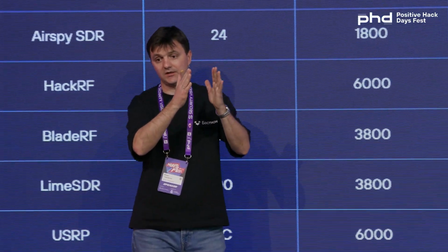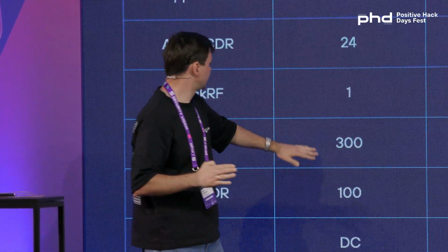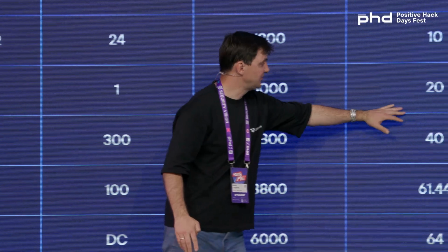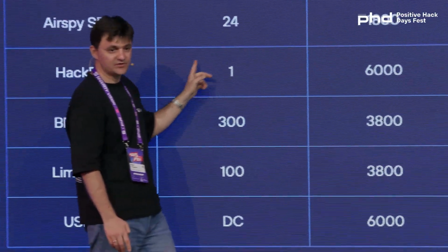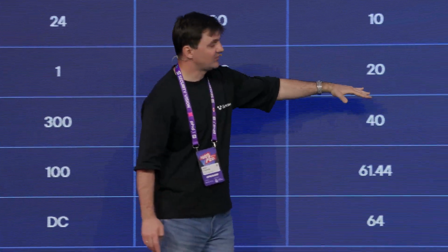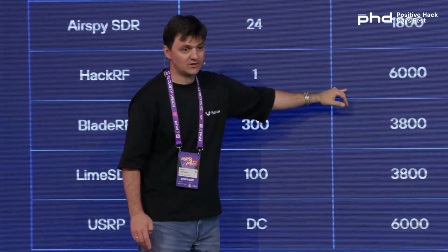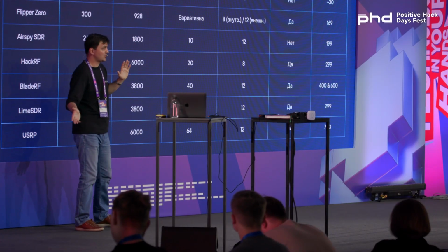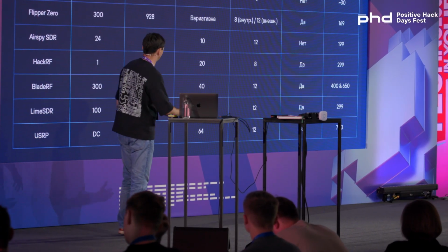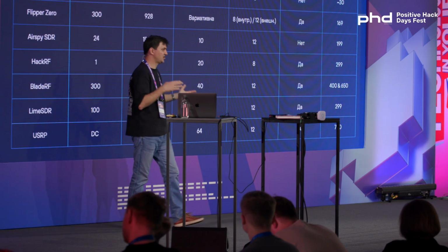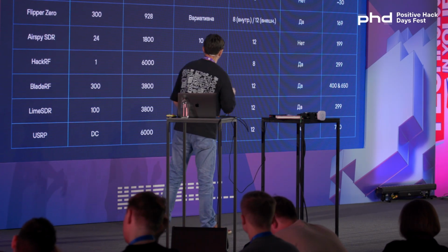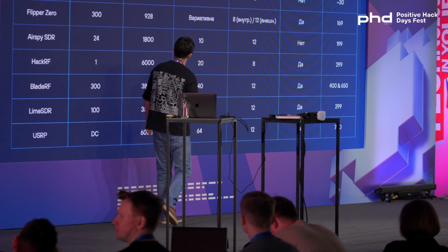Well, it turns out that this device scanned radio channels, not all from 1 to 6 gigahertz, but by parts. In HackRF, by 20 megahertz each. To go through the entire range, it takes 2 to 3 seconds. You can say it's all right, we can tolerate it, but sometimes the signal can be transmitted within a fraction of a second.